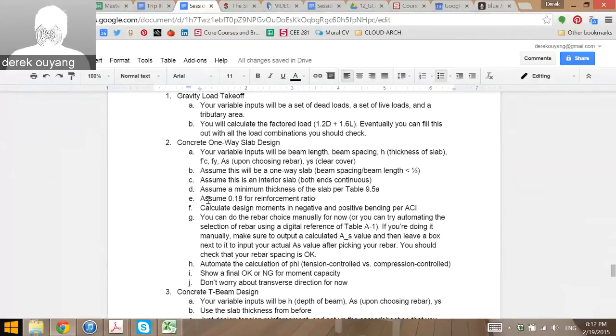Okay. So if you were to continue on to girder, then you would just change your MU to a different formula, but you're still grabbing W sort of from all the gravity loads down, right? And that was that first spreadsheet. Okay. So you don't have to do this for now, but just know it'll be very easy to get to this point, and then you get to your columns, and then you go down the building, right? So you can literally have a whole building automated with one click or with one WU, which hopefully feels really powerful because then you can do so much personal checking and investigation.